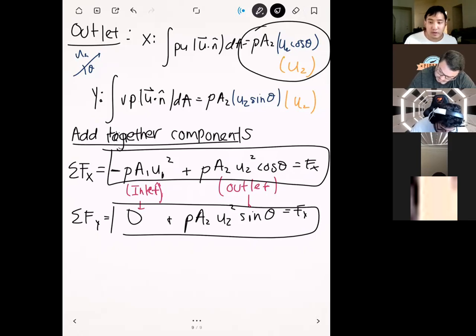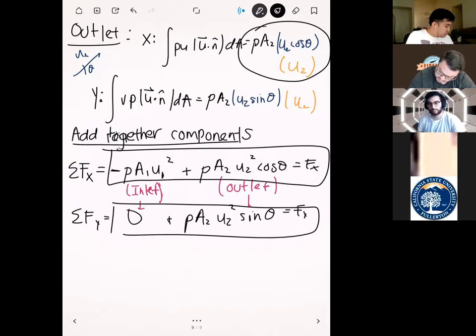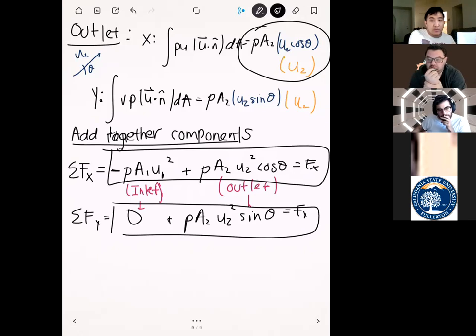All right, any questions on this example here? Explain again the sign convention for the carrying velocities that you're making positive and negative for outflow and inflow. Right, so the carrying velocities here are in the orange ones. And so for the carrying velocities, we make it positive if the flow is at an outlet, and we make it negative if the flow is at an inlet.